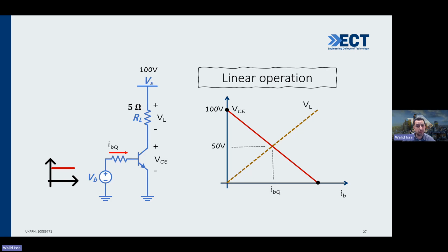So both of them will work, but in reverse action. So the voltage here, 100 volt, will be divided between the load here. The load might be a heater, might be a motor, and my transistor. So I can control the voltage across my transistor or my motor without a potentiometer, just with a small variable current here. But we'll see that change in power dissipation later.